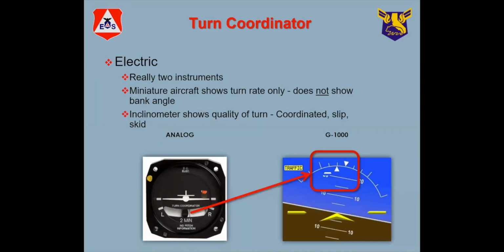Okay, it's the turn coordinator. It's generally run by electric. I think all the aircraft in our fleet here in Hawaii are the ones that are illustrated. I don't think anybody has a needle and ball in the traditional sense. Do you know of any here, Wayne, or any CAP aircraft that have the old style? No, I don't think so. They call this style the wing leveler, because you can kind of use it to level your wings if you lose your attitude indicator. Yeah, all of our airplanes would have this style.